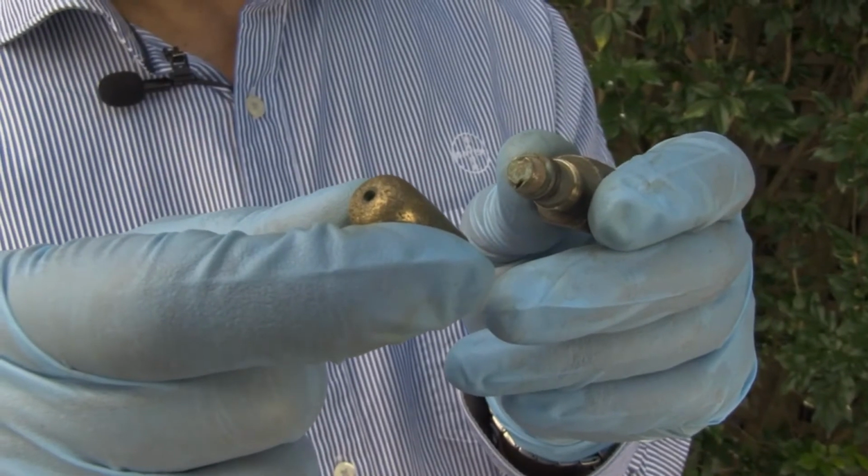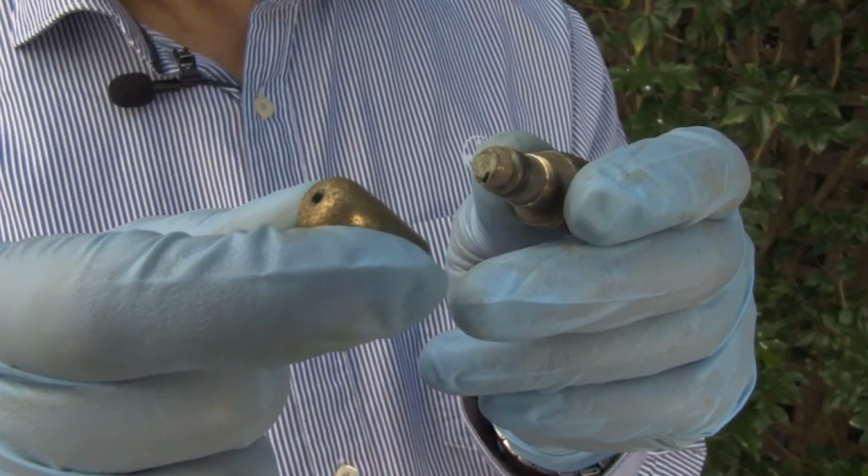So ensuring that your nozzles aren't blocked. One way of unblocking the nozzle you would think would be to use a metal pin or something in the orifice. It's very dangerous. Obviously you can deform the orifice and then create more problems for your spray pattern. The best way to resolve it would be to remove the nozzle and possibly blow some air through it to release the blockage, or something like a blade of grass that's handy that you can push through the nozzle to clean it out. But certainly not an object that is harder than the material used to create that nozzle, such as the brass. So any type of metal would be detrimental to your nozzle and your spray pattern.